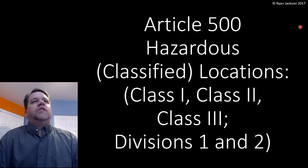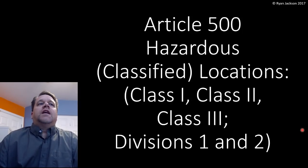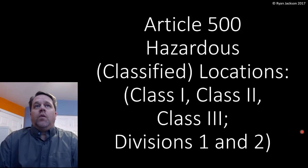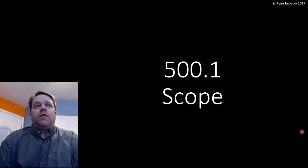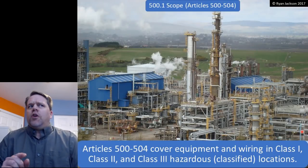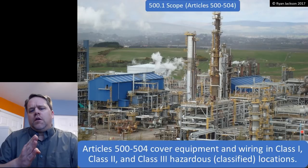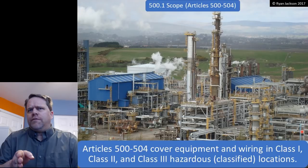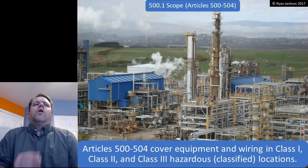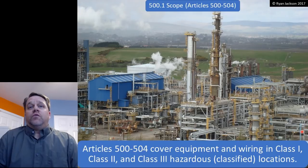Let's get into the NEC. Article 500, Hazardous Locations, Class 1, Class 2, and Class 3, Divisions 1 and 2. The scope of the article. 500.1 contains a scope which is a bit odd because it's actually a scope not just for Article 500, but a scope for Articles 500 through 504, which is a little unusual. Articles 500 through 504 cover equipment and wiring in Class 1, Class 2, and Class 3 hazardous classified locations.